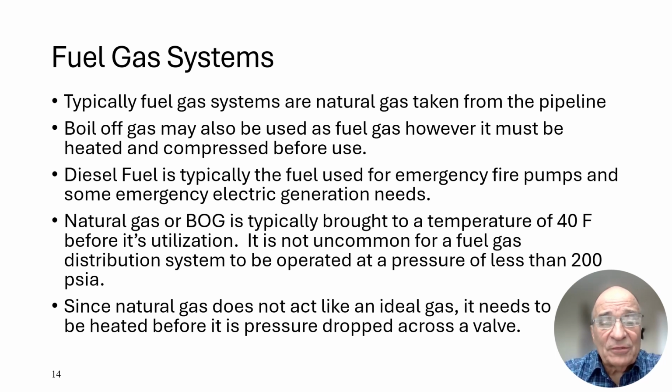And you want to heat it up for several reasons. Gas coming off the pipeline has moisture in it. You don't want to have hydrates form, or you don't want to have freezing taking place in your control valve. Also, you want to make sure that the piping systems, which are typically carbon steel, do not operate below a temperature that is appropriate for that carbon steel. Carbon steel, when it gets too cold, becomes brittle and can fail.